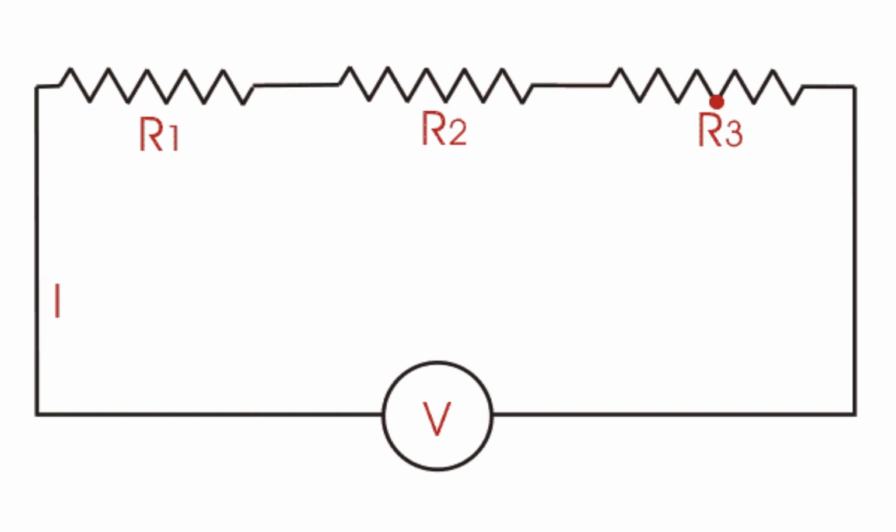For example, assume that a voltage divider is connected to a source of 120 volts and is to provide voltage drops of 36 volts, 18 volts, and 66 volts. Notice that the sum of the voltage drops equals the applied voltage. The next step is to decide how much current is to flow through the circuit. Since there is only one path for current flow, the current will be the same through all the resistors. For example, a current flow of 15 milliamps will be used. The resistance value of each resistor can now be determined.